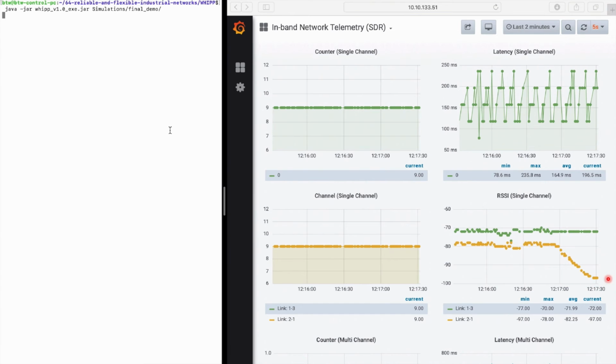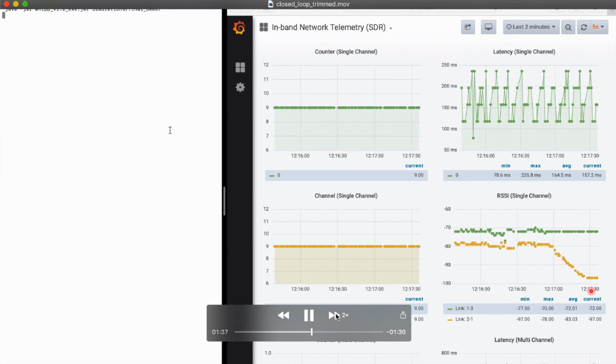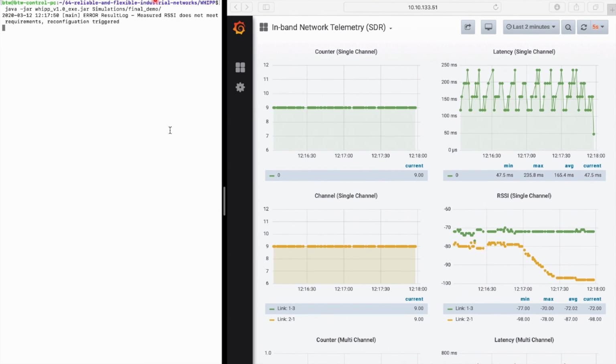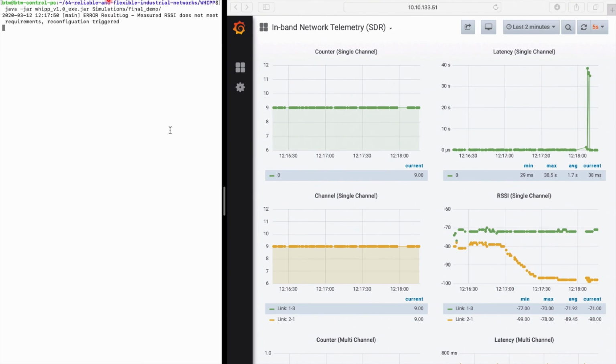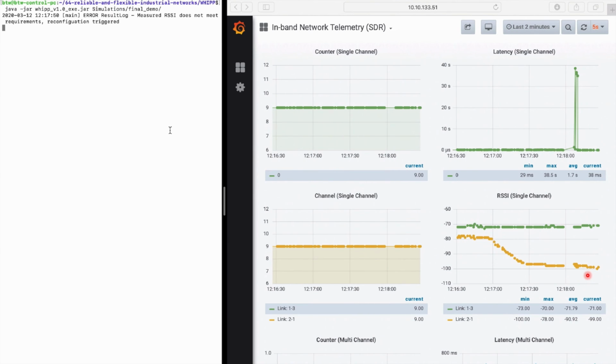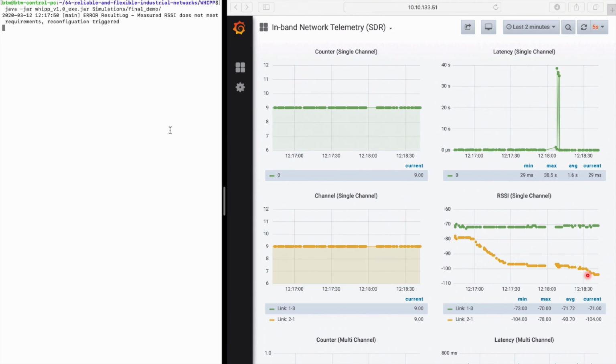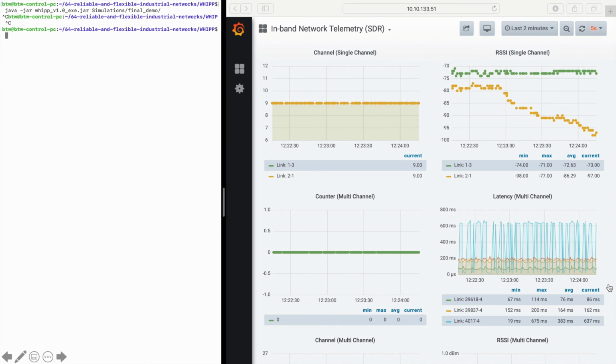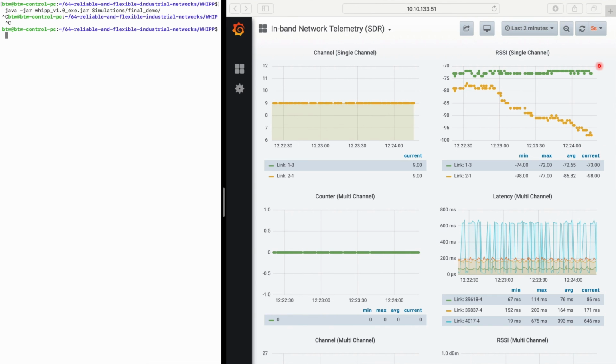We artificially decrease the received power at the RF input port of one of the clients and see that a reconfiguration is triggered when the closed-loop monitoring system is active. In this case, the software-defined radio that is Zigbee compliant switches to a narrow bandwidth channel to decrease the receiver sensitivity. And after the reconfiguration, we can further increase the attenuation and the data stream between the two clients continues. When the algorithm is not running, the communication stops when the received signal strength reaches the receiver sensitivity.